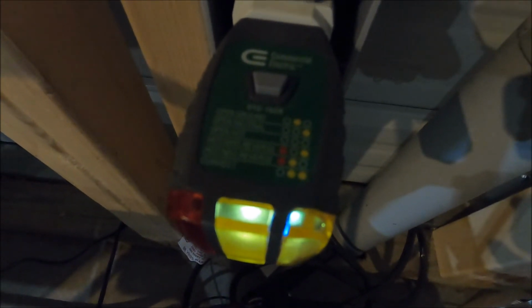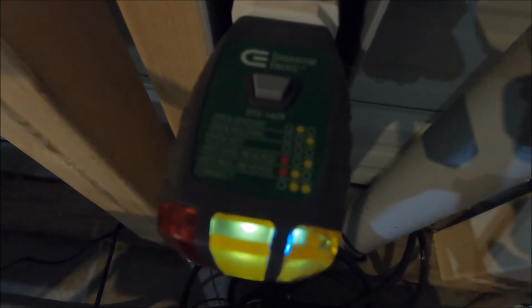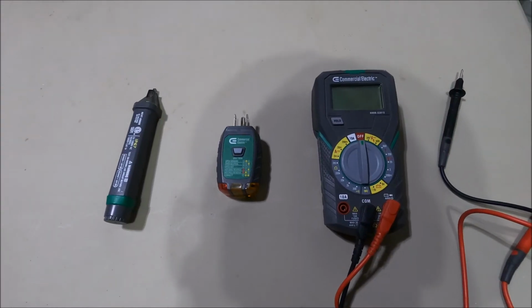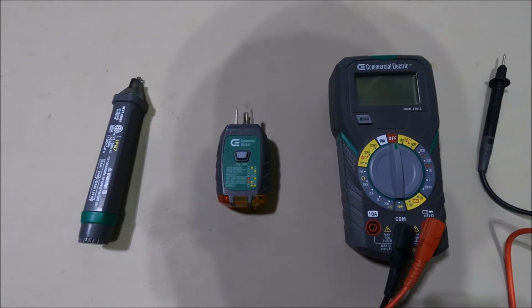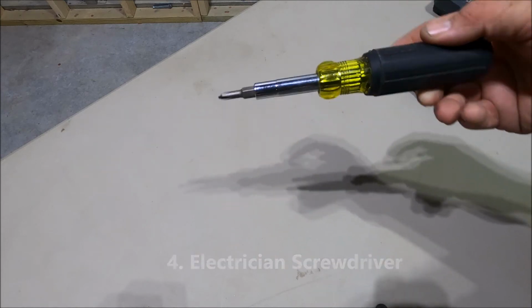There've been times, especially when I was starting out, that I'd be sitting there wiring stuff up, maybe not quite paying attention like you should, and you plug one of these in and the hot and the neutral are reversed or something like that. I never had a problem with the other ones, but generally it's the hot and neutral. Maybe you accidentally switched the wires from the gold screw to the silver screw or something simple. But this will tell you if you've done it right or not, especially if you're starting out. It definitely helps. I actually bought all 3 of these in a set, and that's probably the most economical way to do it.